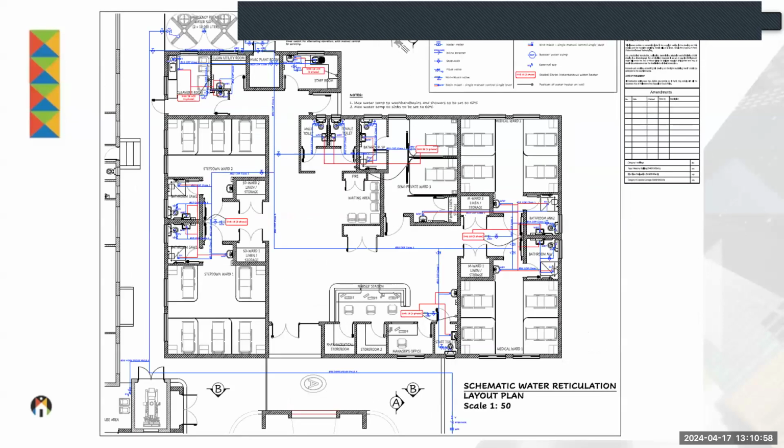Now, although the National Building Regulations do not require us to do a water layout plan, in this particular one I've done one, but that is for a specific purpose. It's also to show the position of hot water in terms of Part XA. I'll talk a little bit in one of the others when we come to Part W or one of the other standards later on regarding the requirements of water reticulation. It is not required in terms of the National Building Regulations to submit such details to the local authority.